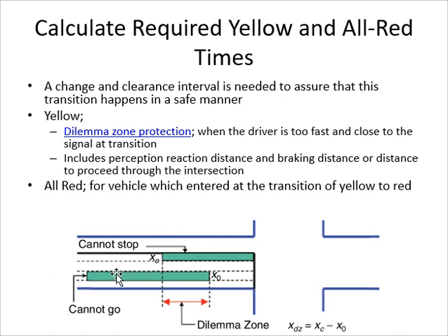Okay, now I think it happens the other way around. People who are even too far decide we want to go, so when they reach the signal, it's actually red. But anyway, this is how the procedure goes. You are assuming the driver will decide on the safer side. So even when the yellow time is still remaining, but it is just the end of yellow time, those drivers who are even reaching the signal at the end of yellow time will also decide to stop.